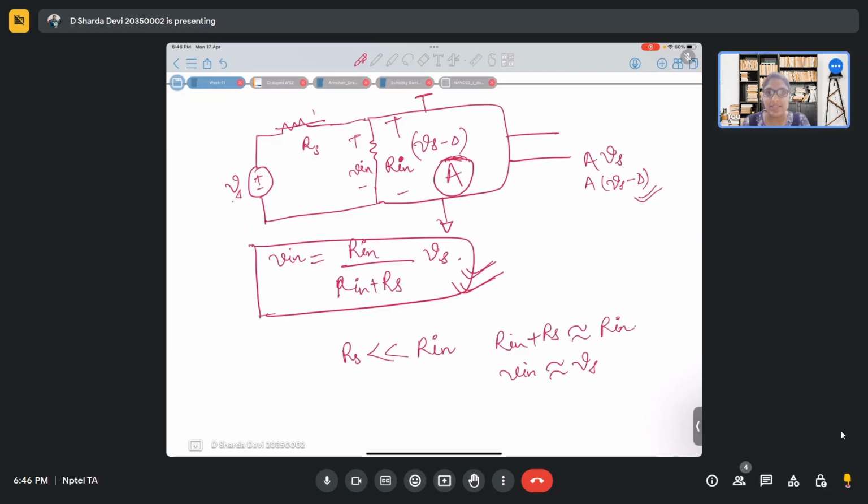This is how we design our amplifiers so that they avoid these loading effects. We want our amplifier to get completely what we are supplying, and also we want our load to get whatever output is coming out of the amplifier. That means your amplifier should not eat any of your output signal. Whole of the output should transfer to the load.